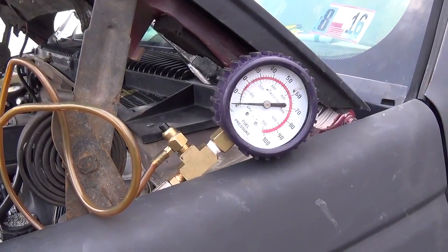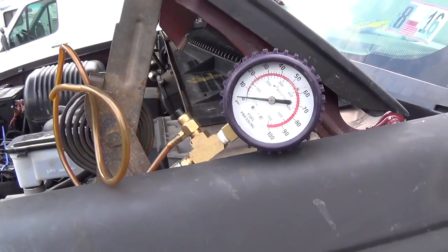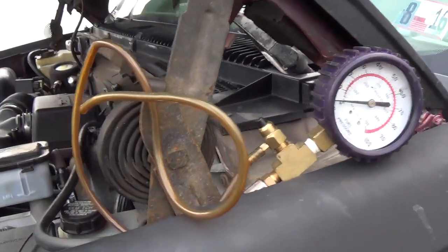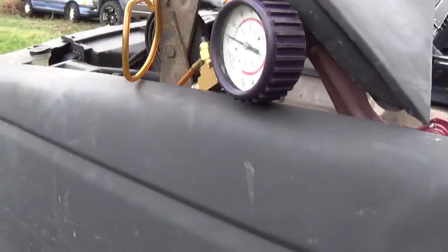So in this case, the tank has to come off. As we know, the fuel pump runs, so we don't have to do any electrical checks. It's simple as that. And the symptom leading up to this, where it had no power under load, it would just fall flat on its face, that is very symptomatic of a fuel pressure issue.